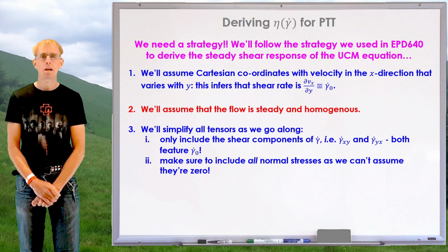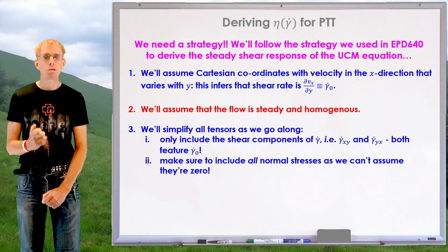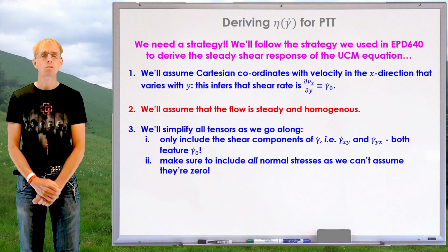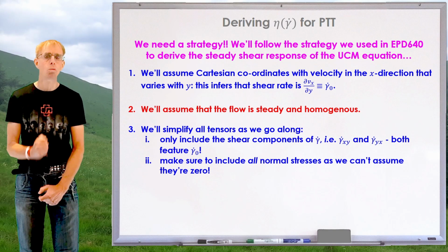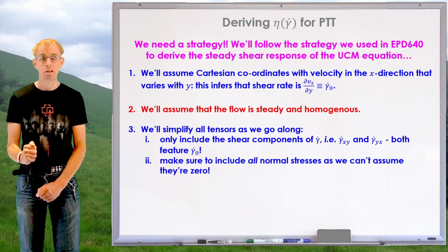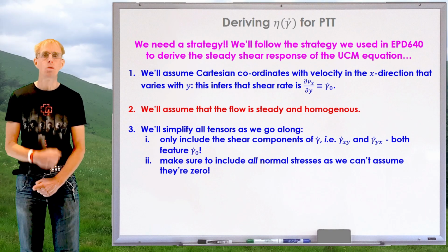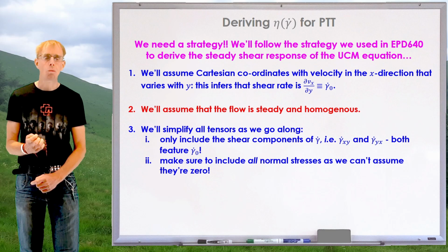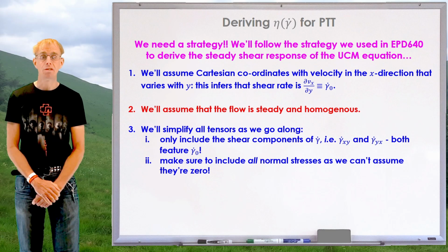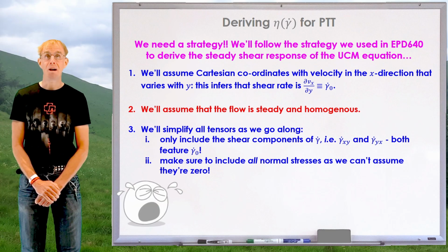Remember also that when we're doing these sorts of analyses, we need to include all our normal stresses a priori at the start, because we can't assume they're 0, because we're dealing with viscoelastic models where normal stresses will probably be generated. Okay, a bit of time out.